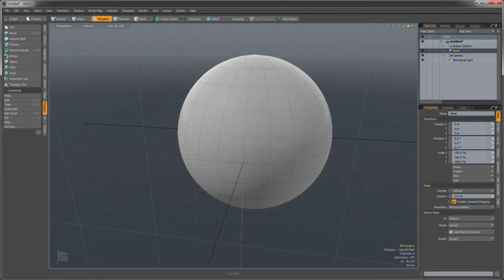The next key skill is selections. You're probably already familiar with the fact that you can click and drag over a series of components, depending on the selection mode you're in, and select them. Some additional tools that I will be using: I'll be using Shift Up arrow to grow out those selections, and oftentimes I'll use the pattern selection, where you click to select an object, hit Shift to select a second object, and then you can use the up arrow to continue that selection.